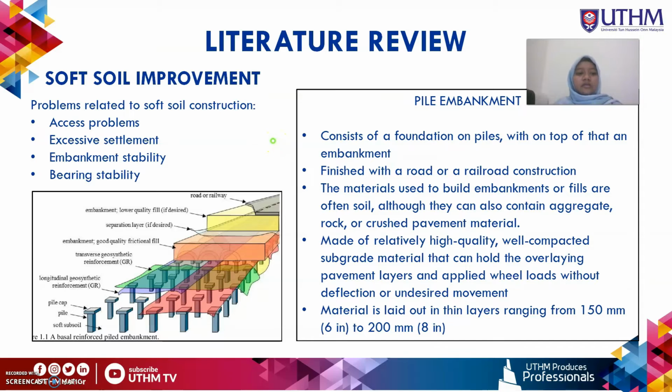Problems related to soft soil construction are normally access problems, excessive settlement, embankment stability, and bearing stability. Therefore, to overcome these problems, pile embankment is used as the soft soil improvement. Pile embankment consists of a foundation on piles with an embankment on top of that. It is finished with a road.